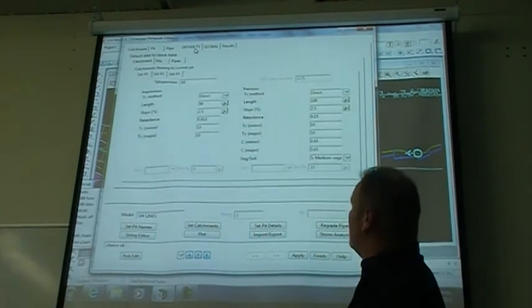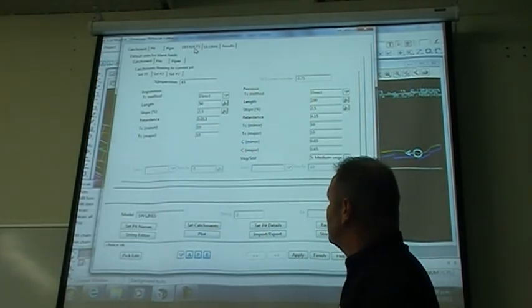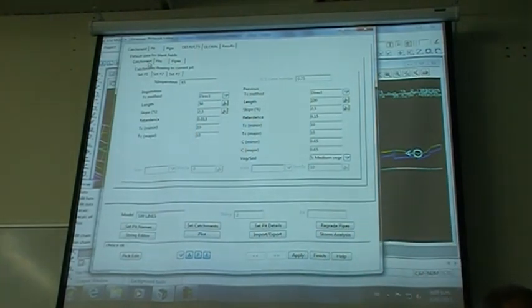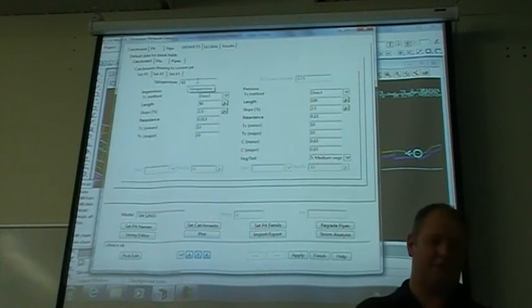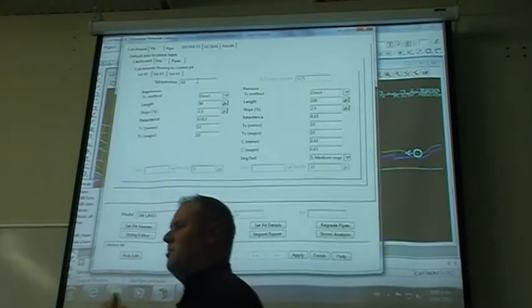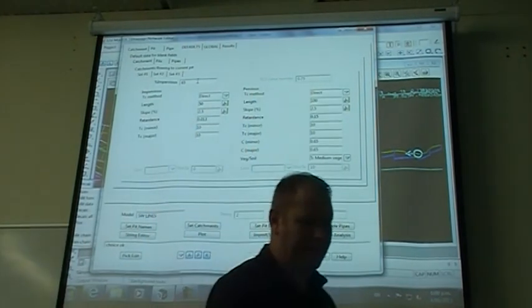Okay, the next one across, up at the top, moving from right to left, is our defaults tab. As you can see, we can set defaults for the catchment, pits and pipes. We're just going to work on one data set. Again, any time it asks you for an impervious, I want it set to 65% and make sure all the times of concentration are 10 minutes, so we get some kind of standardised response in the figures that come out at the end.